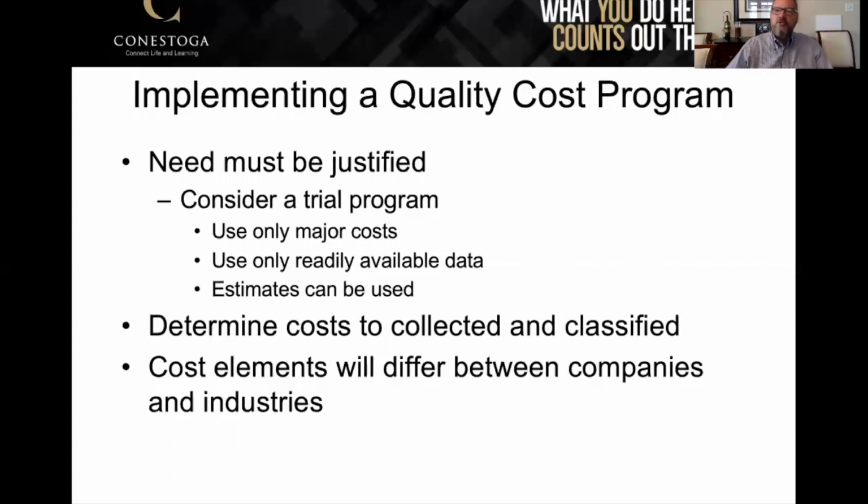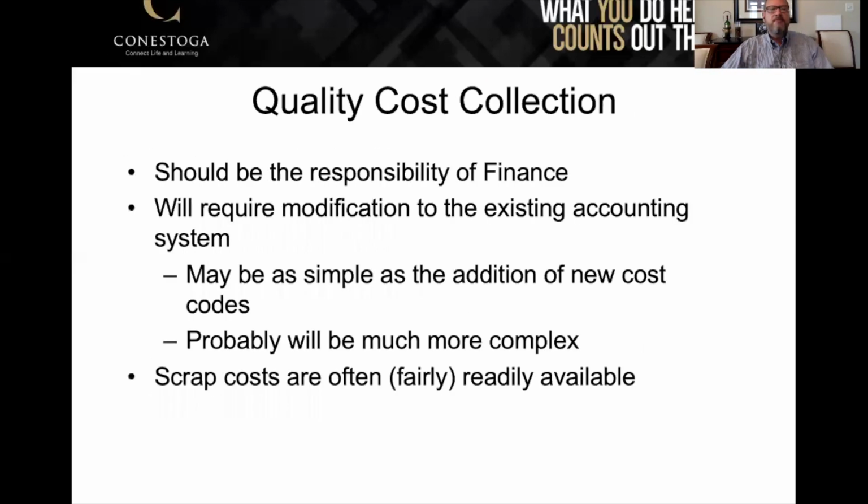And then that can turn the tap off to a large extent for your external failures. And as I said, your external failures will be the most expensive things that you have. So one of the first easy things you can do is I inspect 100% of stuff before it leaves. Now, should you be doing that ongoing? Maybe you should, maybe you shouldn't. It really depends on your environment and a variety of things that are going on. But it is an early first step to kind of stop the gate from making it worse. Keep in mind, inspection doesn't fix anything, right? It just potentially prevents something from getting worse.